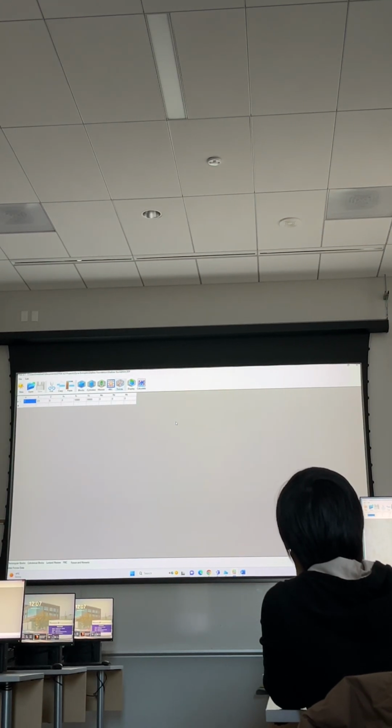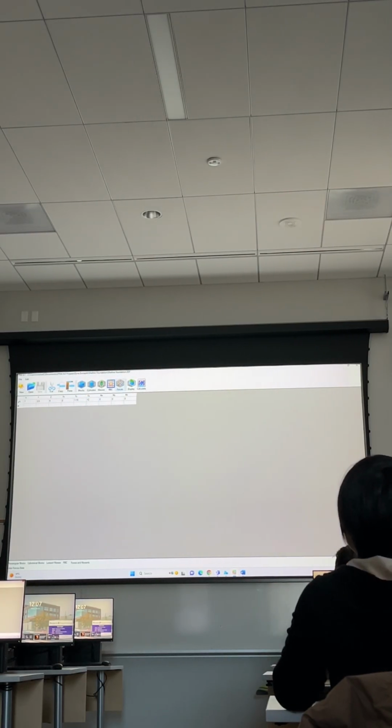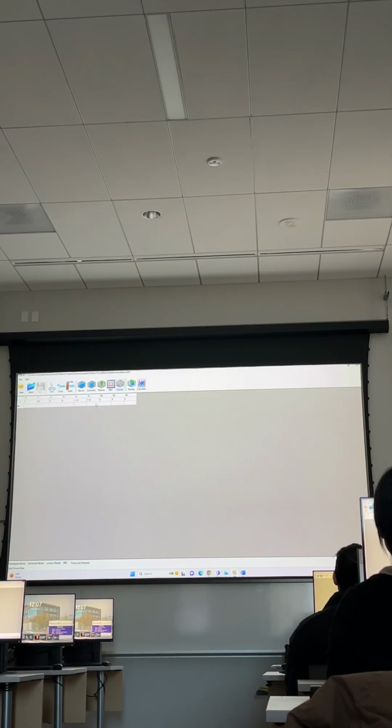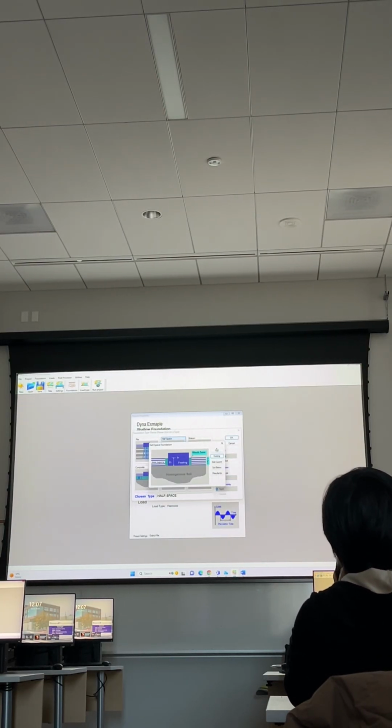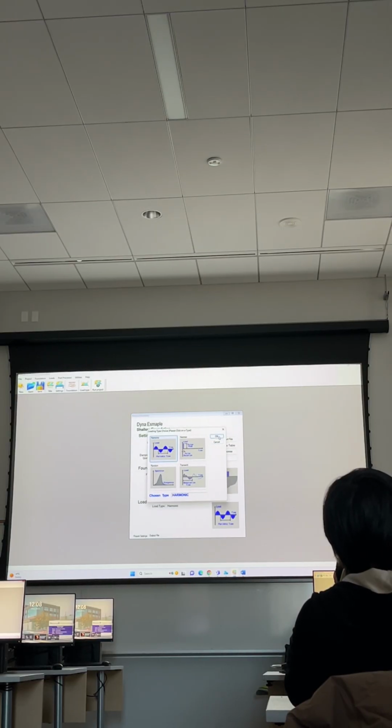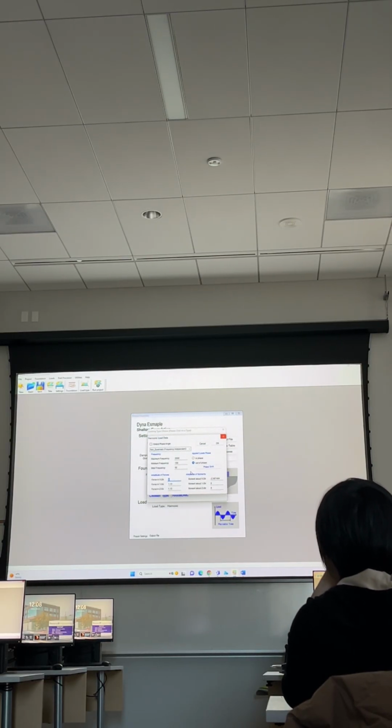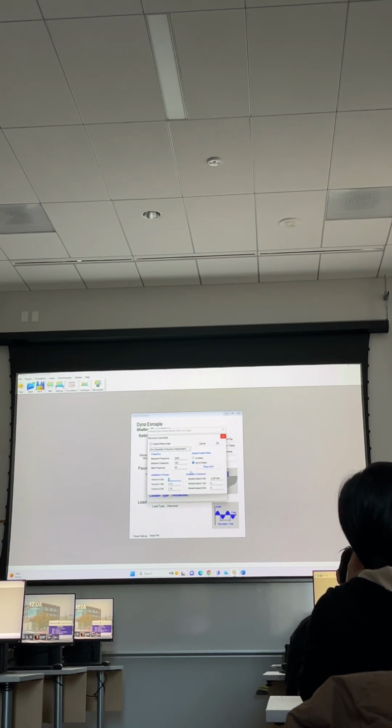Okay, so this value which I calculated right now represents the M multiplied by E, ME. This is the force. I will use this one here. I put 1.13 and here 1.13. Okay? I will save and calculate and then close this one. Everything okay. Go to the load, harmonic load, and now you will find that the force you input before, 1.13. You get the same force here, 1.13, right?